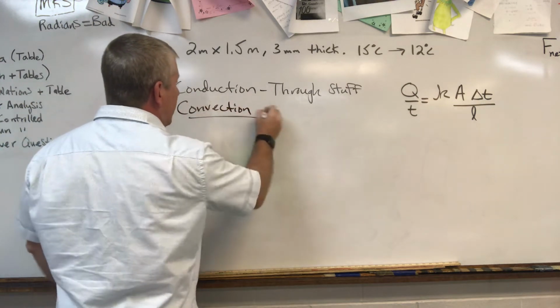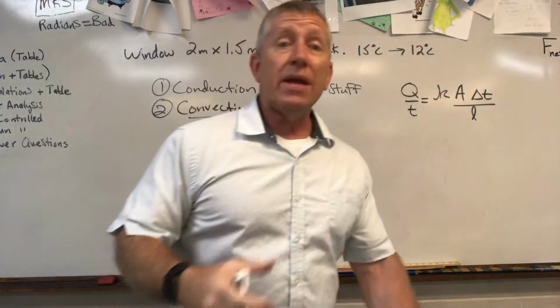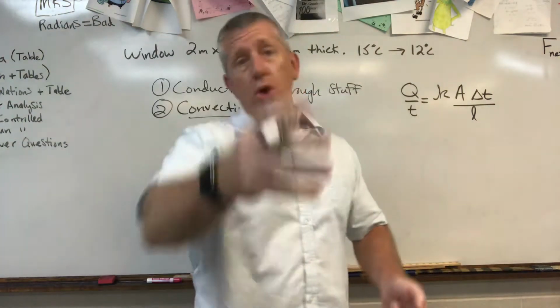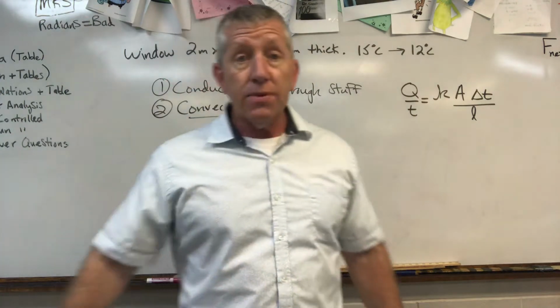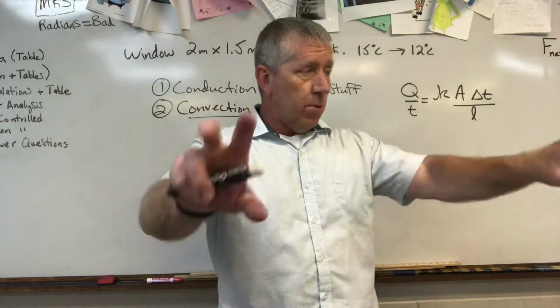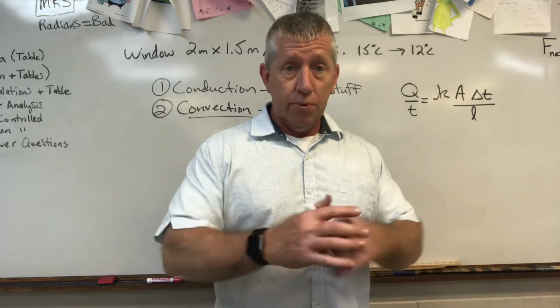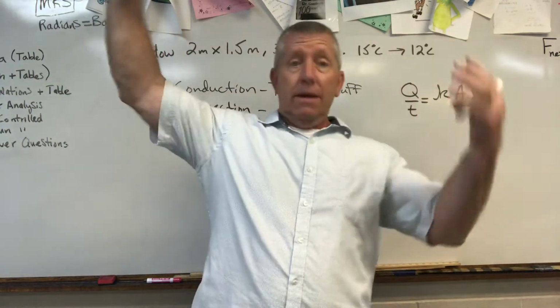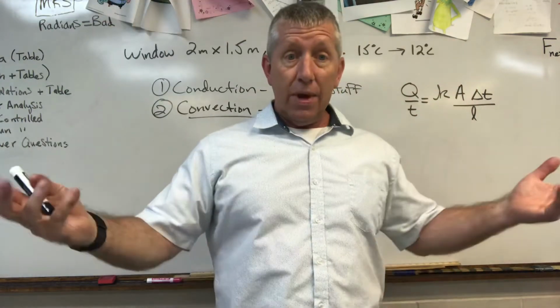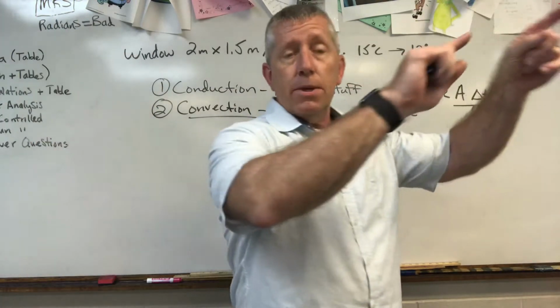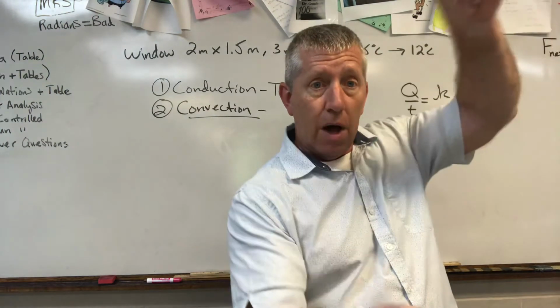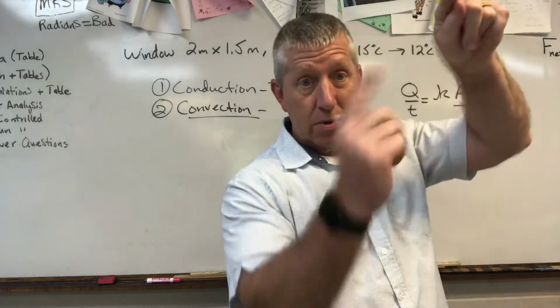All right. There's another one called convection. Convection is based on density differences. Things will move, groove, shake, and bake. You know that hot air always rises. Yes, you do. And so like baseboard heating, it's effective. It's more effective than putting heat coming in through a vent through the ceiling. Because you put the heat down below and it rises, displaces the cold air, causing the cold air to fall. Okay, hot air rises, cold air will sink.